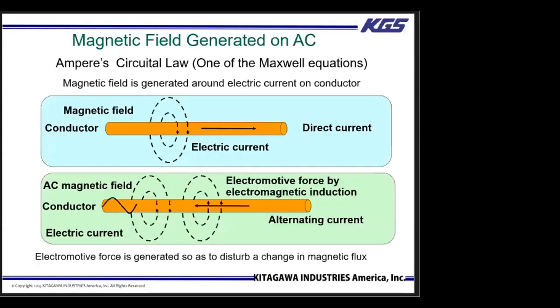So how is a ferrite core effective against unwanted signal noise? When electric current flows on a cable, a magnetic field is generated. Magnetic flux inside the ferrite core is reduced by the magnetic loss of the ferrite, and as a result, the flowing noise current in the lines is reduced. It is these opposing forces which create resistance, and this resistance generates heat.